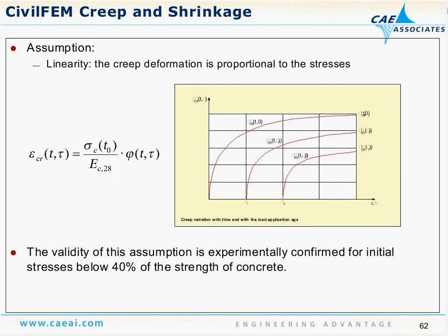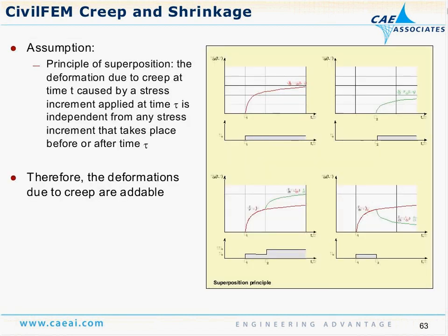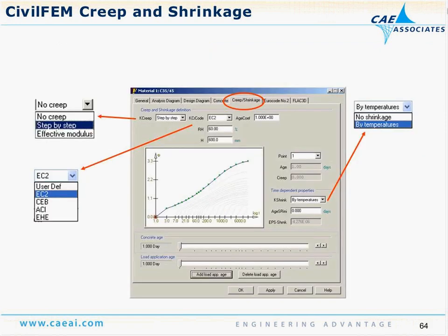The creep definition is assumed to be proportional to the stress, so we have a creep law built in that's stress proportional. We can look at the effects of creep in terms of superposition, assuming that the creep strains can be superimposed with other loads. We can also run a physical time marching response where we're actually modeling explicitly the accumulation of creep, where we're not dealing with superposition.